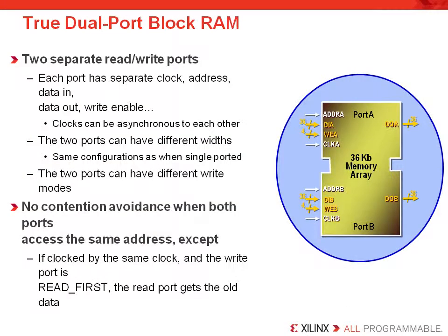You should remember that read and write operations are done simultaneously and independently on both ports A and B. This means that each port has its own clock enable and write enable ports. You should also know that every write operation also performs a read operation. This means that you have the ability to select the operation of the block RAM you want to use. So you can perform a read before write, write before read, or not allow an output change from the block